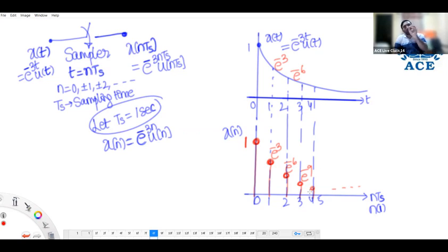We will not show the Ts parameter, we always show the n parameter only. The amplitude of a discrete time signal between two time instants is just not defined. Don't think it is 0, that is wrong thinking. So wherever you observe a pinpoint or lollipop shape, that is discrete. Otherwise, it is continuous. That is the easy way to differentiate continuous and discrete signals.